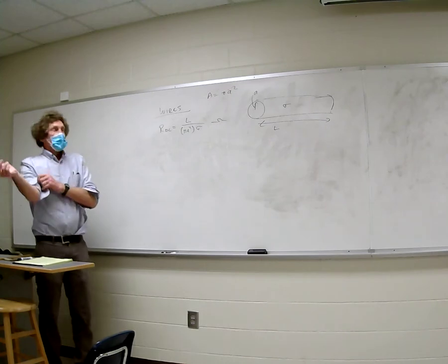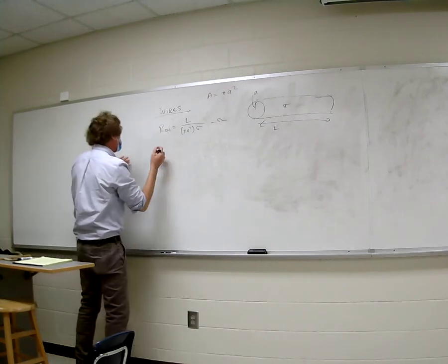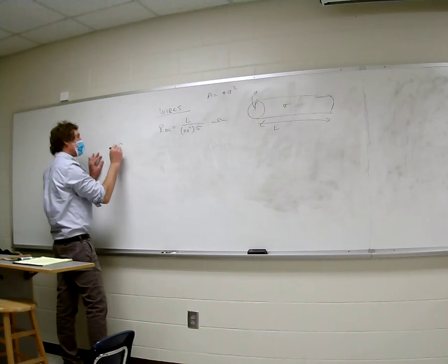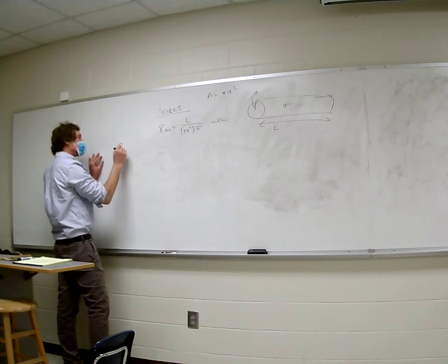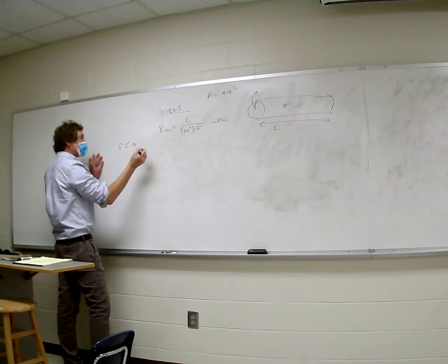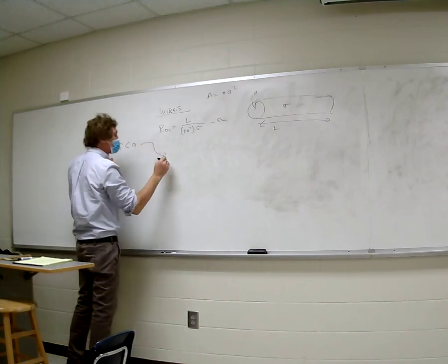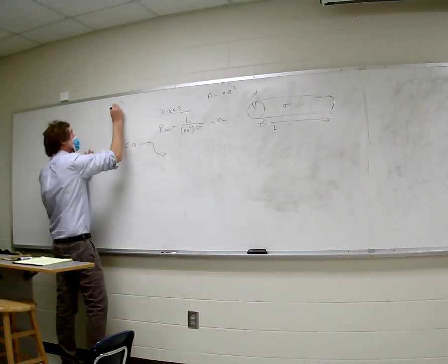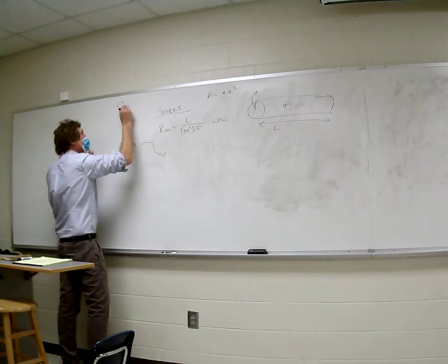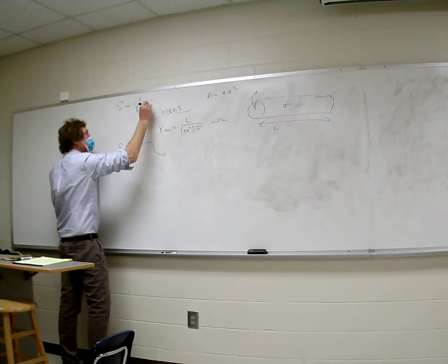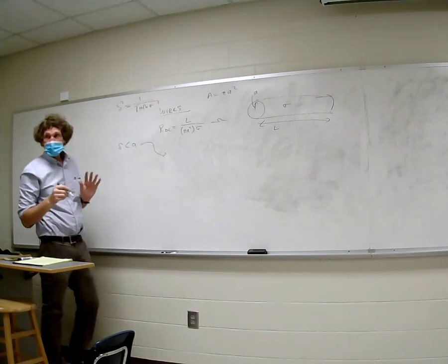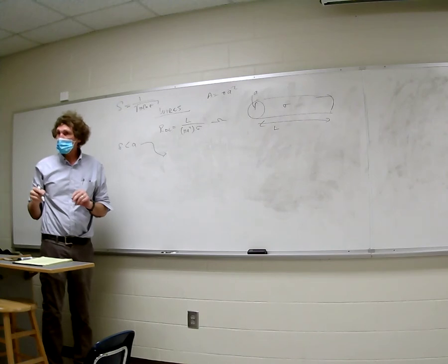Now, that's R DC. Next thing we always look at is, is the skin depth less than the radius of the wire? And by the way, skin depth is equal to 1 over the square root of pi f mu sigma, and you have to know that. That's the skin depth. Is everybody clear on that, class?